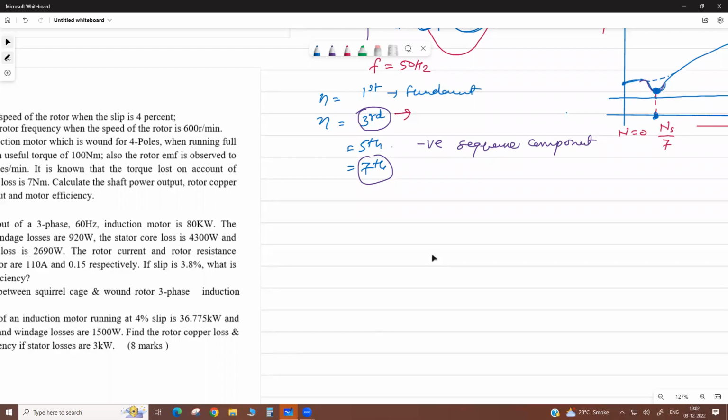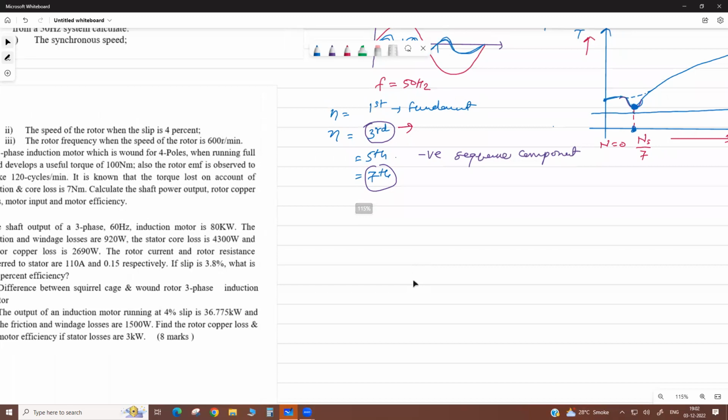Okay, the other reason for harmonics is when we use converters like your rectifier and IGBT, diode, SCR, thyristor. So we are chopping. After rectification, like in a VFD, we have a controlled converter.